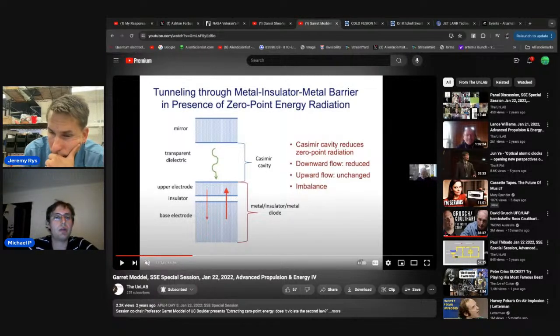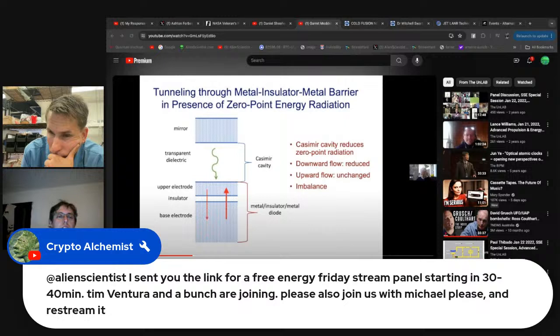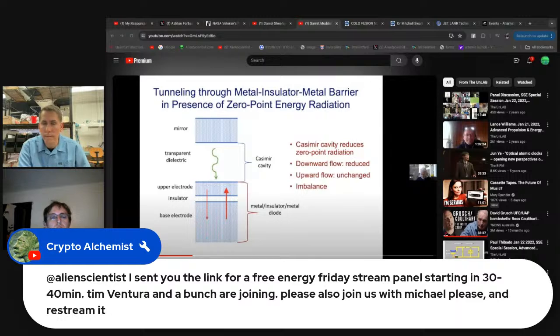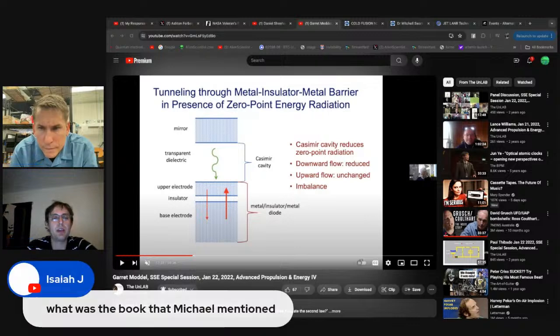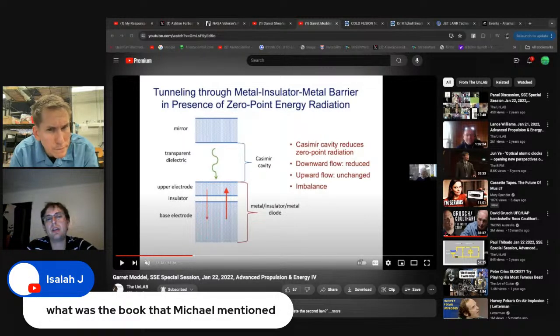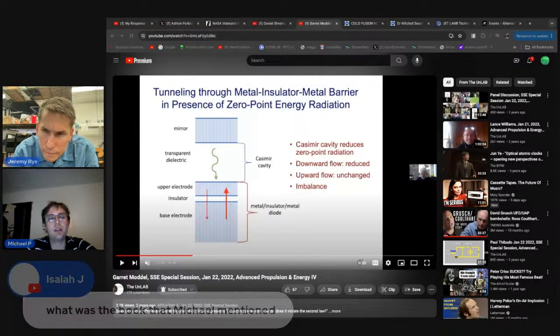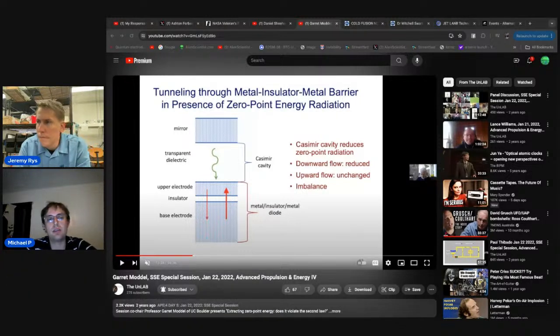I mean, we're talking about a nano layer of insulator, but you can do certain etching processes that'll produce a nano layer, especially on titanium and things like that. And then the transparent dielectric layer is about 30 microns, so that's completely achievable. You can even do 20 microns these days with certain tapes.